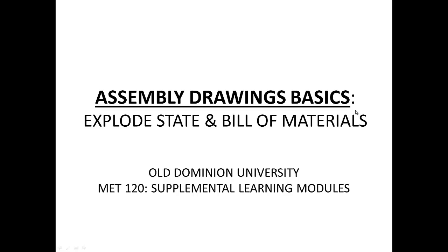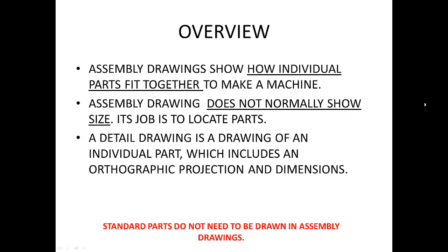You're about to learn something about assembly drawings, something about explode state, and a bill of materials. So first of all, it's important to understand the difference between assembly drawings and detailed drawings. Assembly drawings should show you how individual parts should be assembled in order to make a sub-assembly, an assembly, or on a bigger scale a machine.